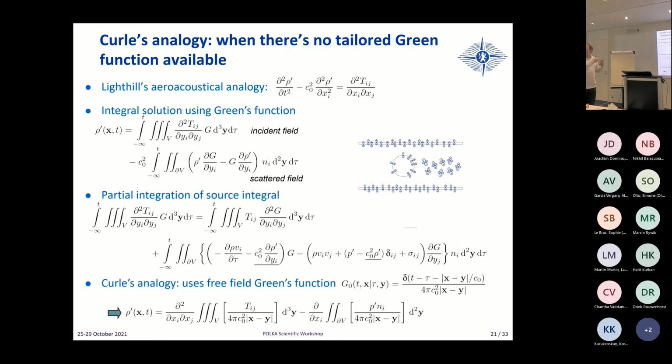They are not explicitly apparent in the form of a scattering integral, but the acoustic reflections are already comprised in here as long as your solution is accurate enough. If you have a solution for p prime that you get from a compressible, high order large eddy simulation, in the immediate neighborhood of the source field, where it's reasonably well calculated, then you are in safe hands. Then the acoustic reflection and the scattering effect of the surfaces is comprised in your source term.